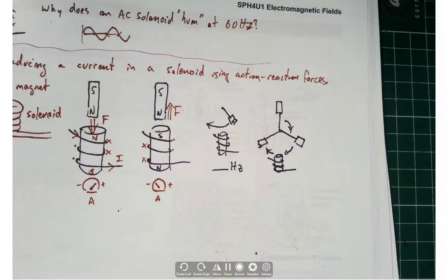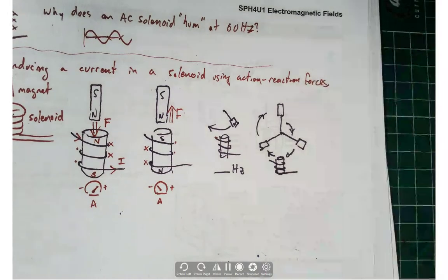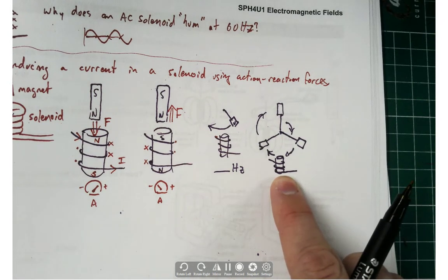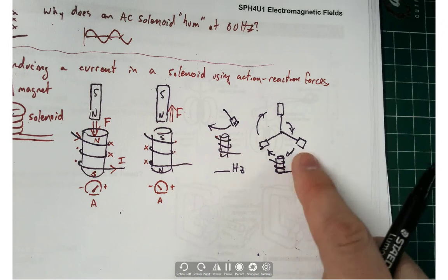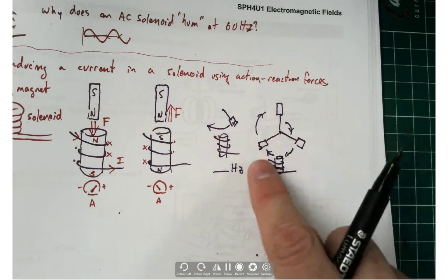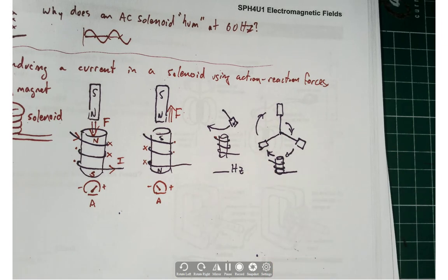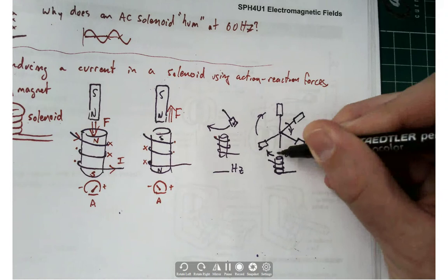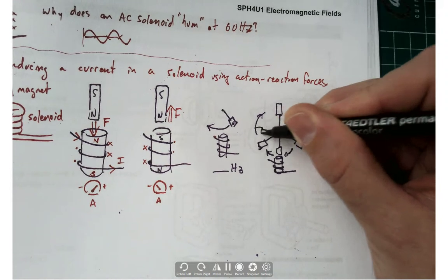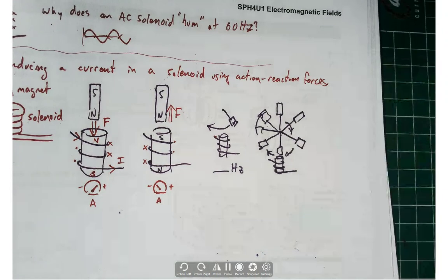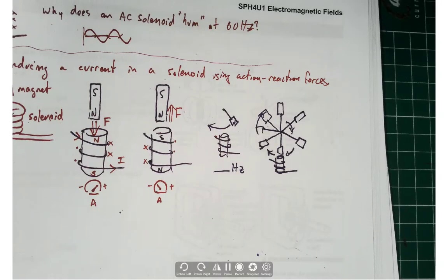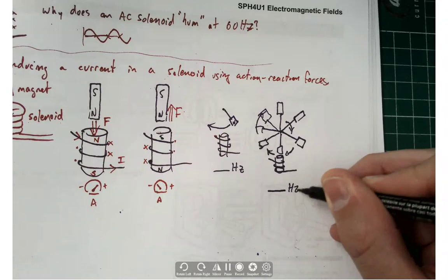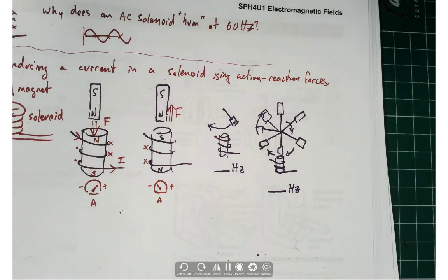And of course, as I'm drawing this, you imagine this wouldn't be so hard to set up. I could set up the toilet paper roll on the floor, and I could suspend a bicycle just above this thing. We could mount magnets on the outside hub of a bicycle wheel. You're picturing what I'm saying? In fact, we could even up our game, and put one magnet at every spoke of the bicycle wheel. Wouldn't that mean there are more magnets constantly coming towards and going away from that solenoid? We could spin the wheel at just the right speed so that a magnet goes past that solenoid 60 times per second. That's something I could regulate.